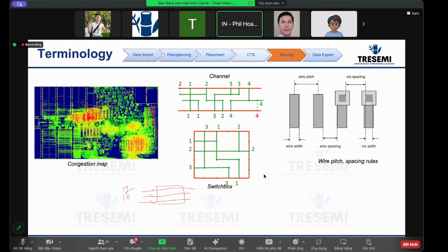So the point being, without the timing, it will probably route cleanly because they are blue around, so it can just go through all the blue and then go to this target. But if you do this, then the timing becomes worse. So the router algorithm would be, I give priority for timing, meaning when I route, I need to make sure that the timing critical signals are treated well. So it is a combination of timing requirements and the congestion.